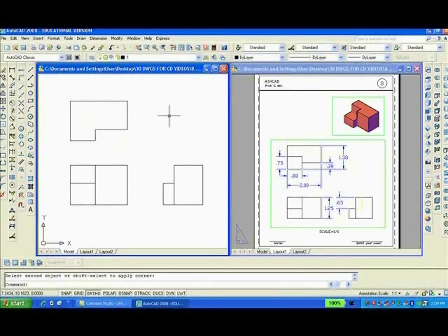And I have to offset. O, enter, 0.75, enter this line, and I want to fill it here. Escape, F, enter, that line and that line. So the drawing looks correct, and what I should do now is to move. M, enter.